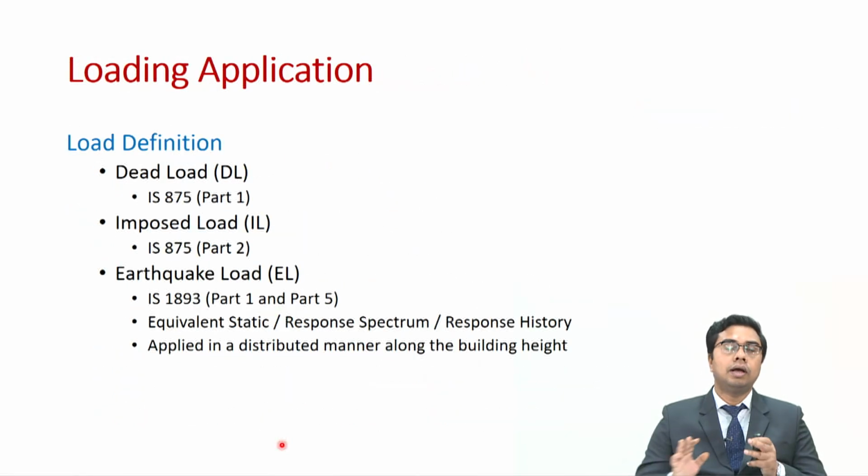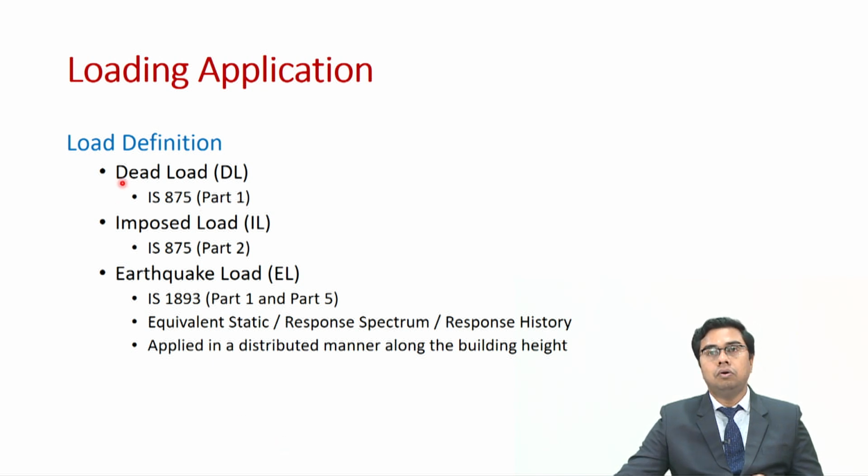Okay. Once you have the analytical model ready with you, then it is high time to apply load on the analytical model. So, what are the loads that we will be applying? We will be applying dead load, imposed load and earthquake load. Dead load, as it is clear, it is mostly from the self weight of members and the load which is always going to be present over there. So, this will be obtained from IS 875 part 1.